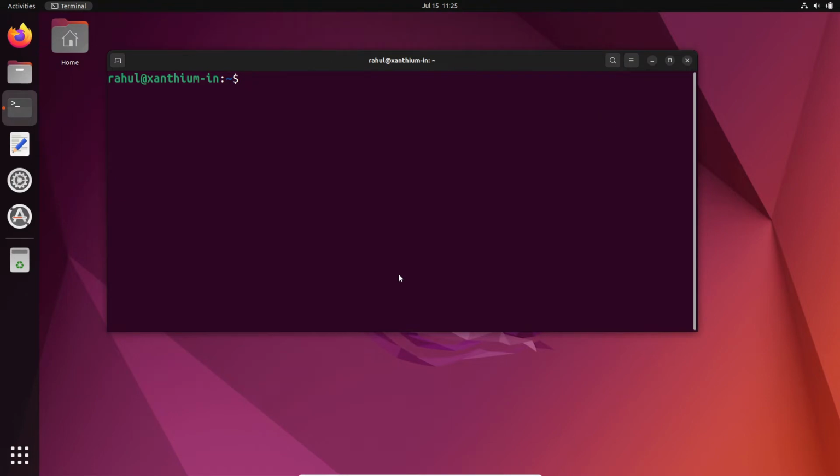Now that we have installed PySerial, it's time to program the Arduino. So we can connect our Arduino to the Linux installation through the USB port. After you have connected, you have to know the name of the serial port. For example, in Linux, it should be /dev/ttyUSB0 or something like that.